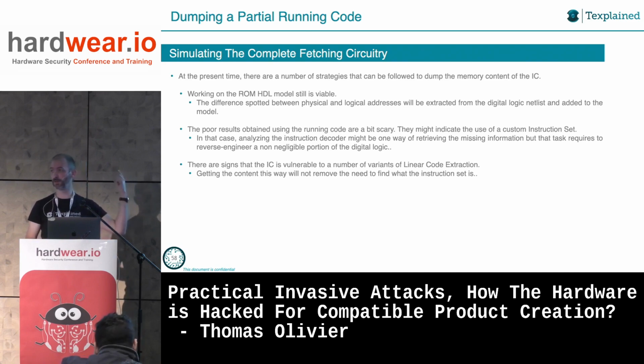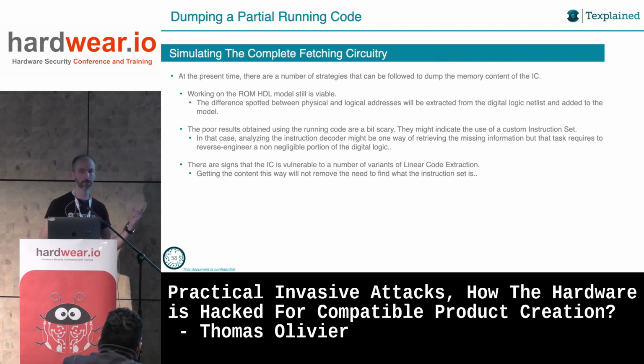By the way, you can do linear code extraction attacks on this chip too. Linear code extraction attacks are invasive, and they are made to dump the full contents of memories. It means that basically we could have full RAM and full flash extracted like this. But still, if I have a binary but I cannot understand it, that's bad. I start to suspect this chip has a custom instruction set, which is not very nice. You have a binary and you have no idea what kind of instructions you need to find inside.